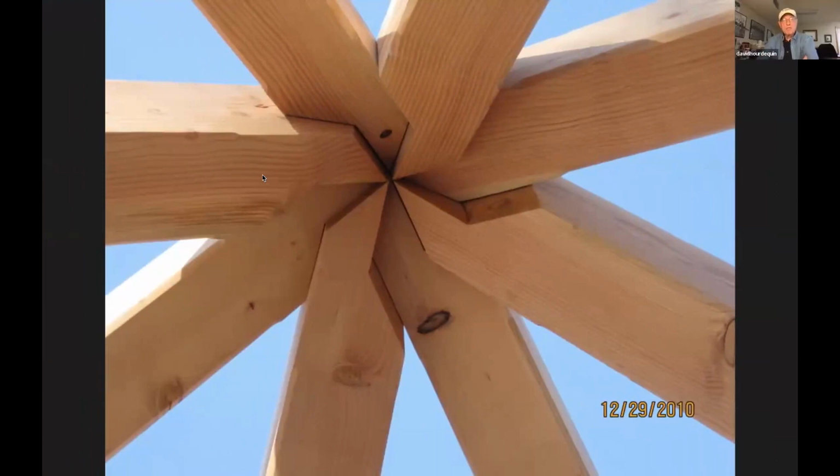Those are all toe screwed from above, right, Josh, as I remember? That's right. Yep. So they all nest into each other, and then once everything's planed out, you can screw around in one direction. Then we usually go the opposite direction so that each member is screwed into the one next to it in both directions. So we have 2 toe screws in each member looking down on it. One goes down to the right, one goes down to the left in each joining timber. So is that right? As I recall. Yeah. That's right. Yep. Okay.